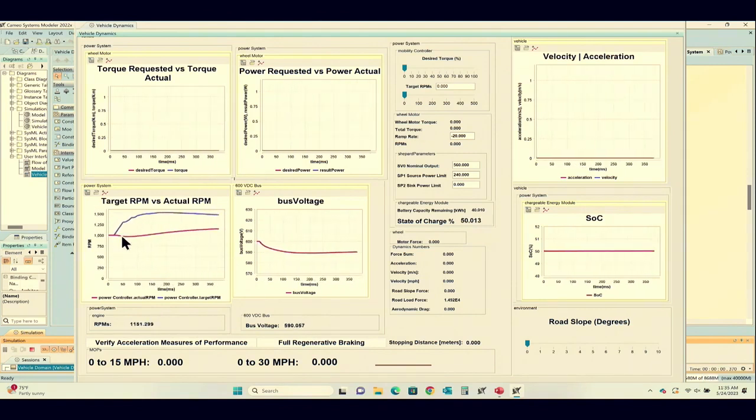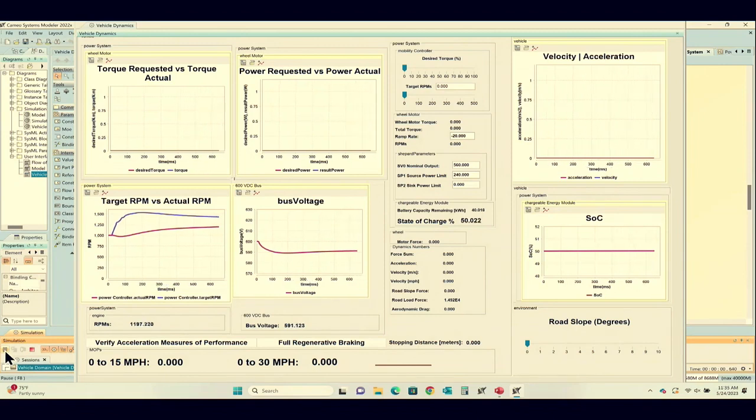So a little bit of wobbliness there. This is somewhat interesting, but when I pause that, notice this red line right here. That was actually the rotation of that generator. When this started out, we had some immediate power consumers that caused this voltage to drop. That was the result of the counter torque placed on it: the RPMs of the engine actually dropped due to that drawing of power. So that's what you see, that dip right there. But then the blue line is the target RPM that was calculated with a parametric.